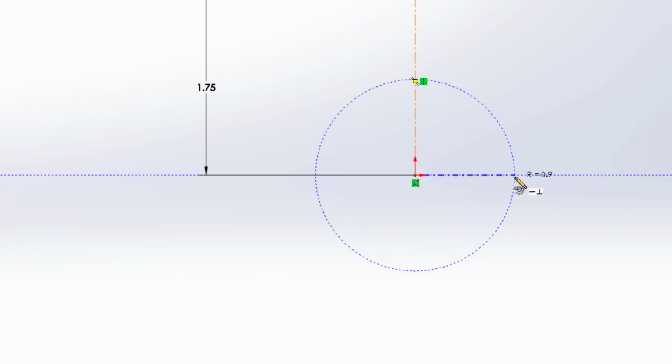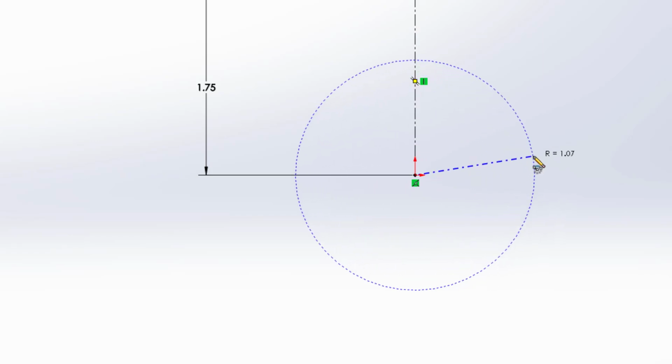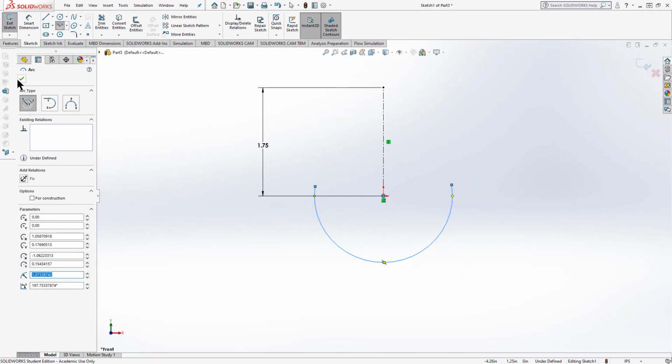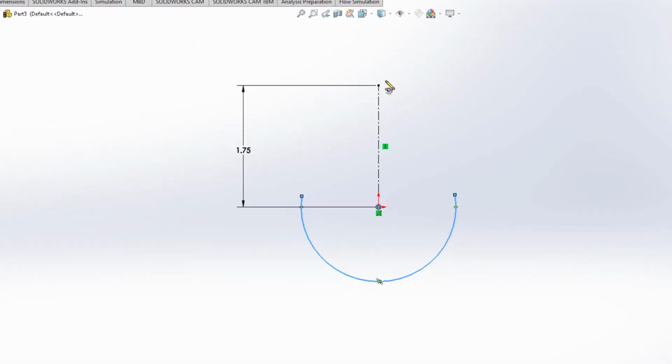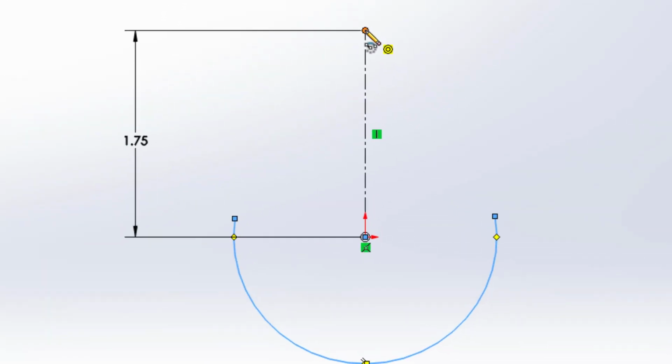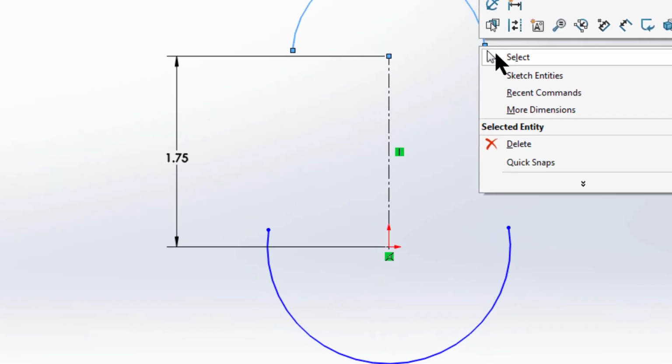I'm going to drop the middle of the bottom lobe on the origin, extend it out somewhere above vertical. And I'm going to click once, drop it, and you'll see me pull it out and drop it a second time, again above vertical. When I'm happy with that arc, I can come right up and do the top arc, same way. Click once to drop my center point. Click a second time to drop my arc, and I draw my arc coming around here. I'm not really concerned where they go.